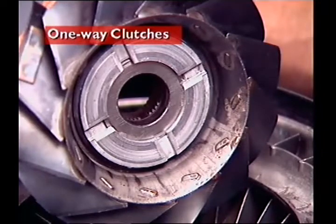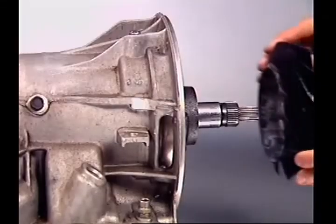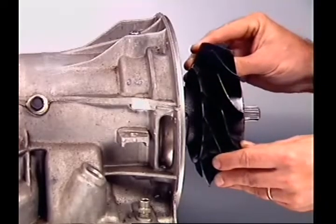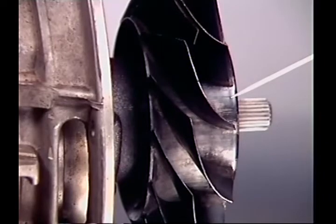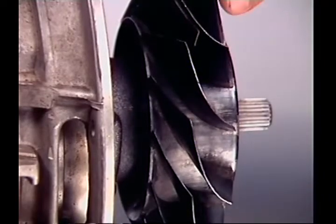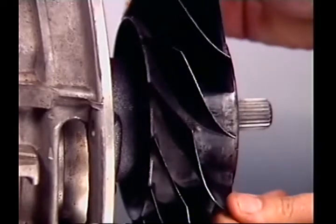In the Sprague type one-way clutch, the inner race has a central spline. It locates on the stator support shaft to hold the race stationary. The outer race is part of the stator hub. It turns with the stator in the direction of engine rotation.